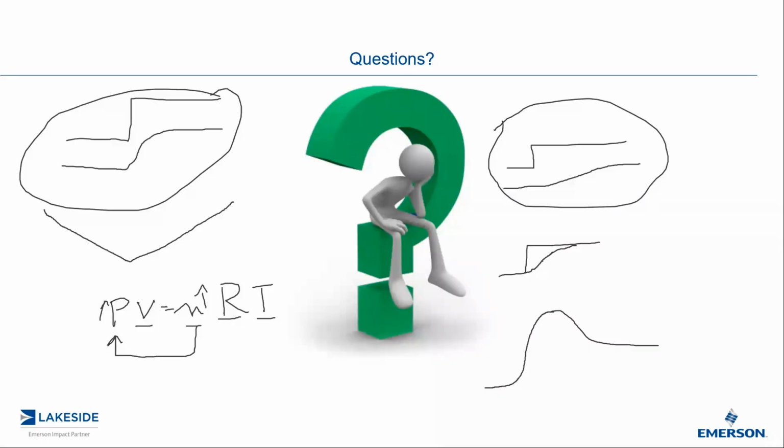So if your PV is oscillating, and again, taking a look at my screen here, if my PV is responding like this, like a shark fin pattern around my set point, and my output is operating like a triangular pattern, that's a sign that my valve is sticking or has some sort of deadband or hysteresis or sticking, probably by this much.